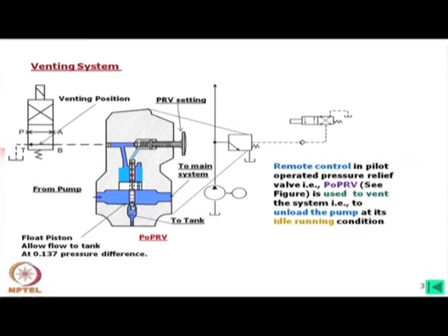And at the bottom, this passage is connected to another path in which this stem is extended, this piston is extended, and apparently it is closing this valve. What else do we see in this stem? There is a hole also inside, and some sort of light spring is there. This one is a light spring and there is a hole. That means this is directly connected to the end of this.